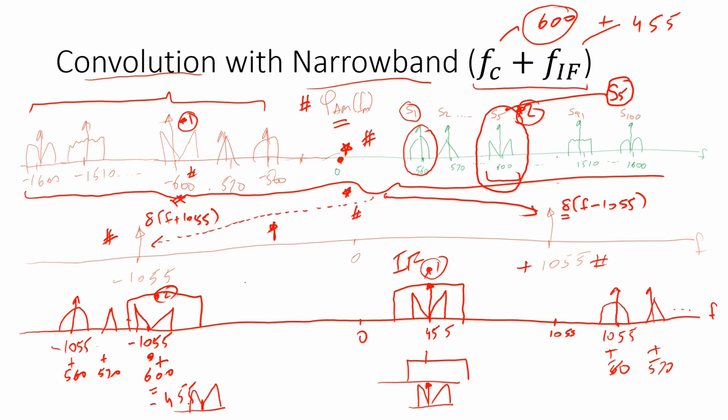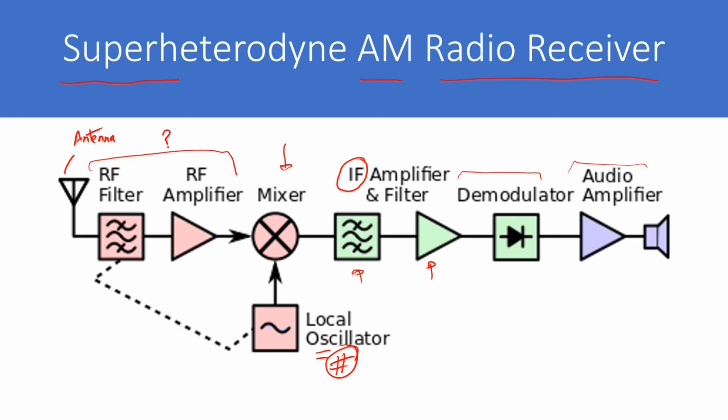and this is around 455 carrier frequency. So this means that at this band pass filter at intermediate frequency over here, we would be left with A plus M5 of t, that is the fifth station, and it is basically at cos omega IF t at intermediate frequency, right?